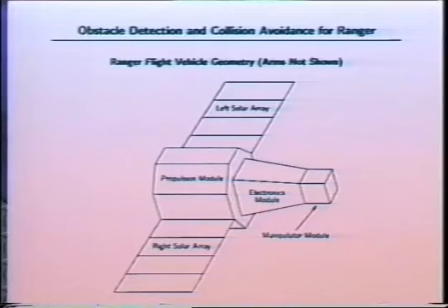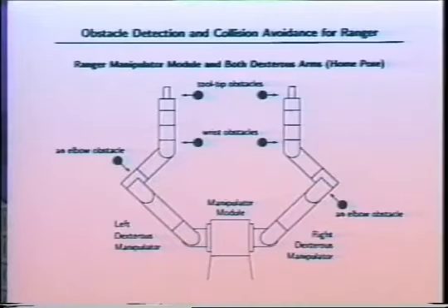In our approach, we surround each potential obstacle with a safety zone. Collision avoidance is accomplished with a new method developed at JPL that uses virtual spring and damper forces to repel intrusions into this zone. Because Ranger has no proximity sensors, simplified geometric models of the arms and obstacles are used to calculate obstacle distances for computing the virtual intrusion forces in real time.